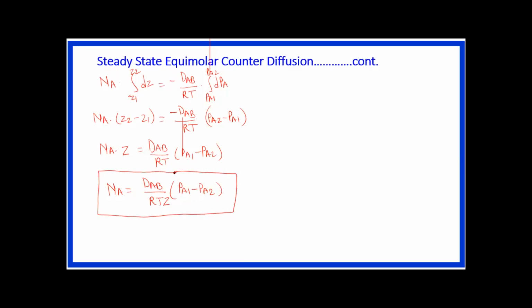of partial pressures. So if the data is given in the molar concentration or molar fractions, then you have to replace this partial pressure in terms of concentration. And we know that PA and CA relationship, right? So generally C equal to P by RT. So likewise, we can replace this terminology and we can calculate the molar flux of component A.